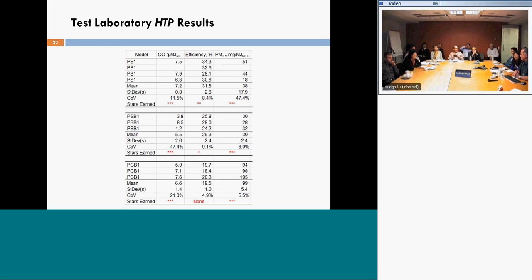Okay. So the efficiency is a ratio, so you have to pick a number on the top and you have to pick a number on the bottom. So which ones shall we pick? There are some questions later, but I can show you a slide about that. The direct answer to your question is the heat gained by the pot during the test, which includes the heat gained by the pot itself and that went into the water. And we actually replace the water in the pot to make sure we know exactly how much heat is gained at all power levels. So we can determine quite precisely how much heat would be gained if you continued to cook. And based on that, we can actually predict when it would boil, or how long it would take to boil at any particular amount.